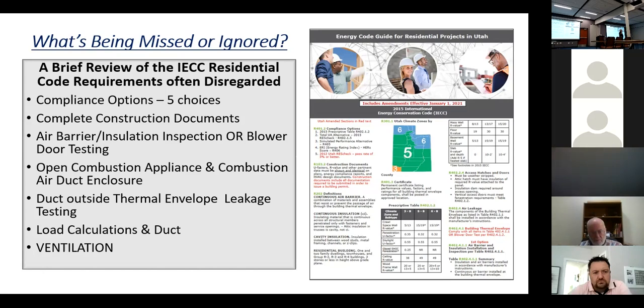Which means if you have a $400 power bill in the summertime for cooling, up to 200 of it, you're throwing away because everybody insists on putting the air handler and the duct in the attic. If we bring it inside the envelope, our heat gain is 0. Right?